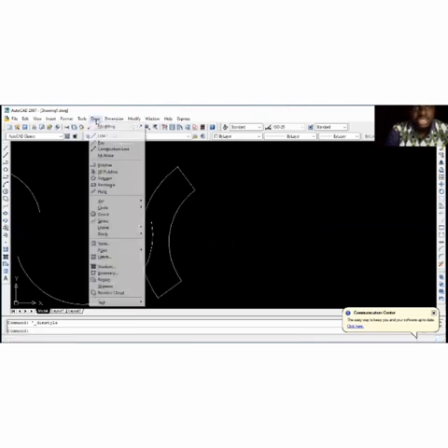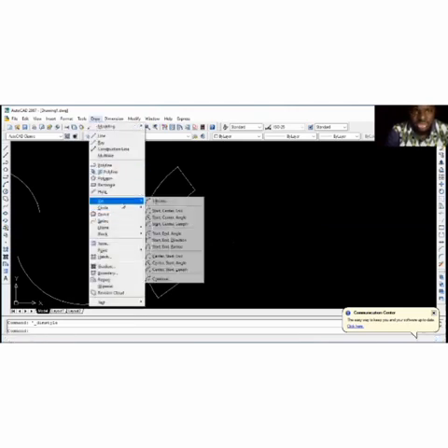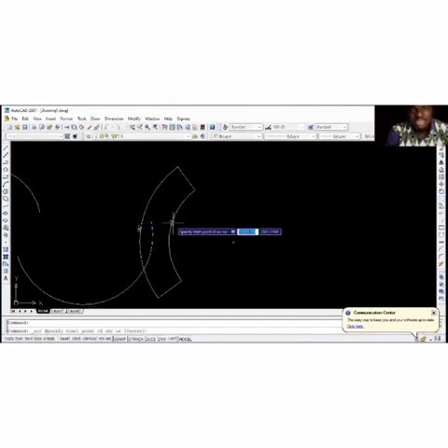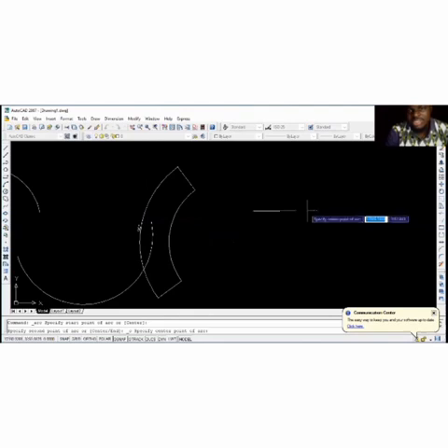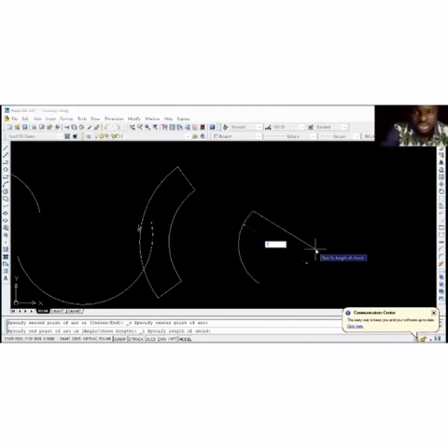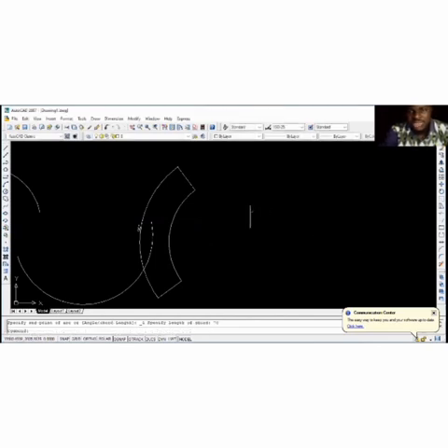So now let's take another option of the arc command where we have the start, center, length. Now it means we have been given the starting point of the arc. We left click, center of the arc. This is the center. And then the length of the arc. We have been given a length of, let's say, 70. And that is enter. So you can see it's very small. It means the length of the arc or the length of the chord of the arc is given as 70.